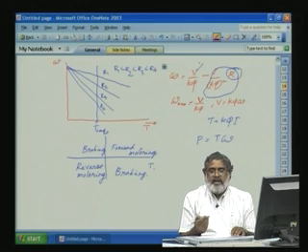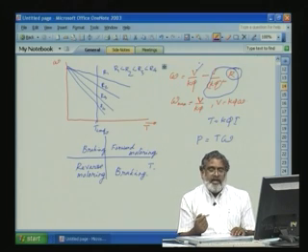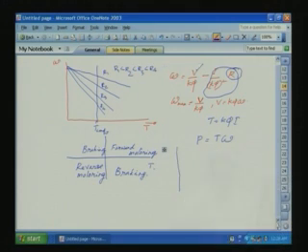We have already studied how we can control that variable DC voltage. So, let us take when the voltage is controlled, how the speed torque characteristic looks. This is torque, this is speed. R is the armature resistance. Let us say for one speed, as the torque increases, because the armature resistance is there, slight droop will be there. But this is the omega 1 due to V1. Now, if you reduce to V2, omega 2 will vary. So, we will get a parallel curve here.